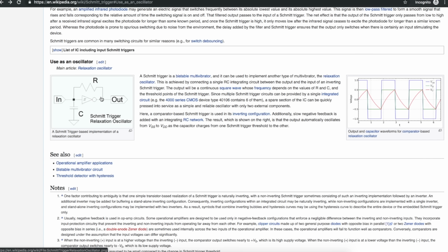So now the output, being logic low, is going to sink current through this resistor and discharge the capacitor. When this voltage here gets low enough, the input of the Schmitt trigger is going to see a logic low, switch the output to a logic high, and again source current to charge the capacitor through this RC network. So you end up with an oscillator. The capacitor is going to discharge down to the Schmitt trigger's low threshold, then start charging up to the Schmitt trigger's high threshold, and so on. And you're going to get a sharp logic output, high and low, at whatever high and low voltages this gate can drive, close to VCC and close to ground in the case of a 74HC CMOS inverter.